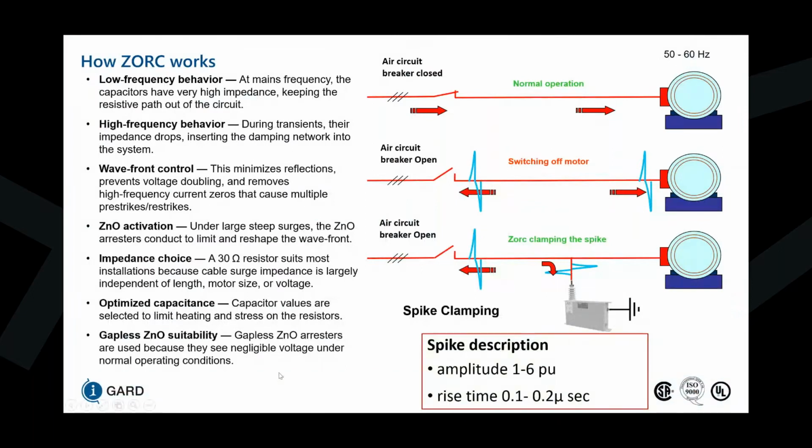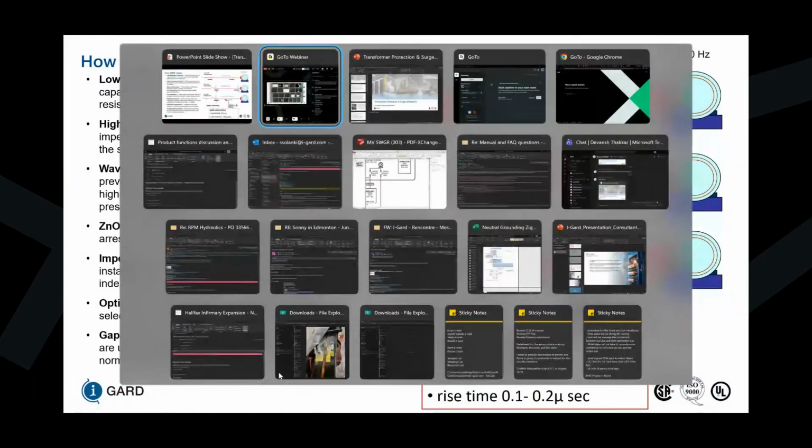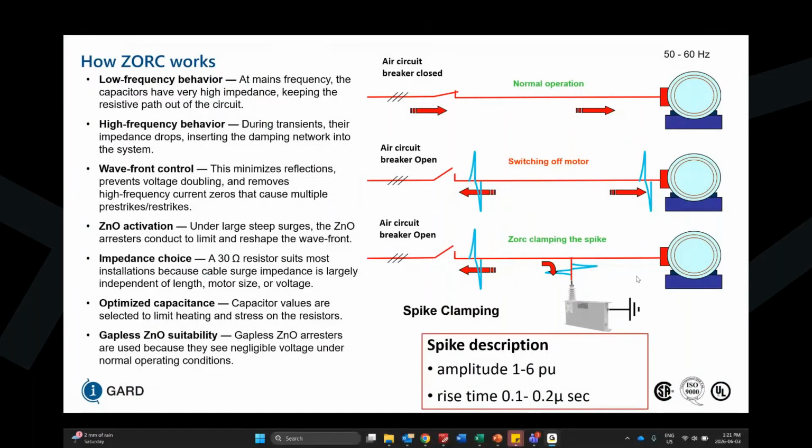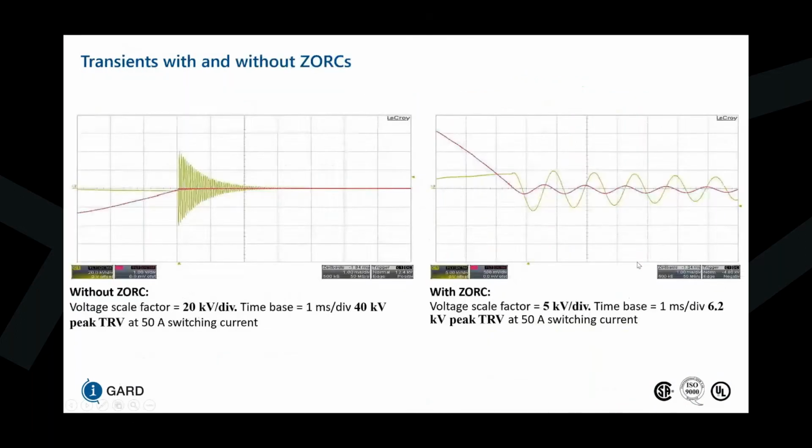Are you talking about this graph? Well, let me see. Red and yellow, okay. So I believe that the yellow is your phase voltage, which is what's causing that high level of transient overvoltage.